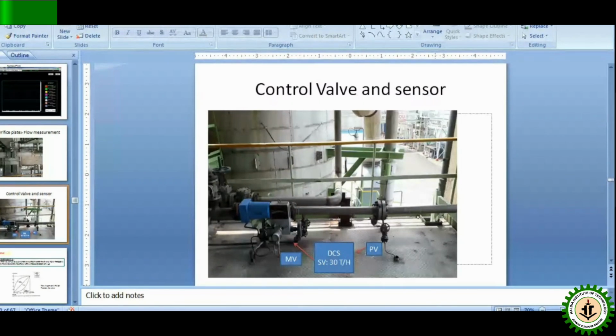Then when this 4 to 20 milliamp signal comes over here, it is converted into pneumatic signal by the help of an electropneumatic positioner, which converts 4 to 20 milliamps to 3 to 15 psi or an equivalent pressure rating, if there is a booster relay and other things available. So now it goes to the final control element, the control valve, and it works.